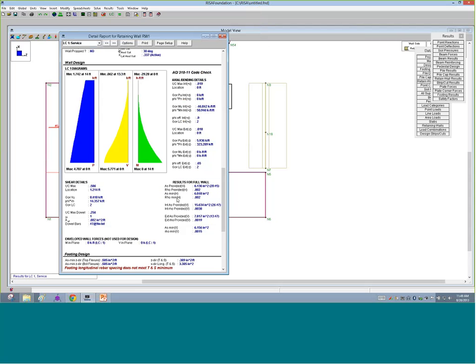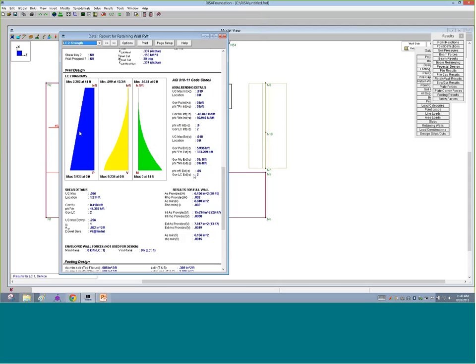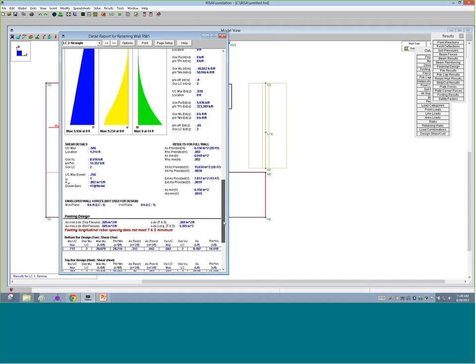So if you ever find in here that you say, hey gosh, that says 0, but I see that it shows axial, probably we're underneath that threshold. In this case, we can see that 5.9. If I jump over to the service level here, I can see that 5.9 was governing in the exterior portion, and then in the interior portion of that reinforcement, it was actually the moment that's governing, so this threshold wasn't met for the axial. With more realistic loading, you might find that this doesn't happen as often, but if you ever do see that, that's a good clue.